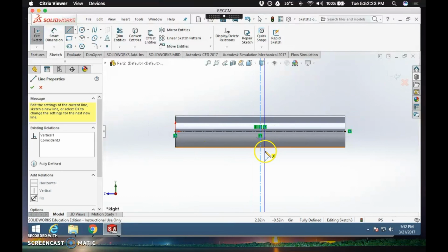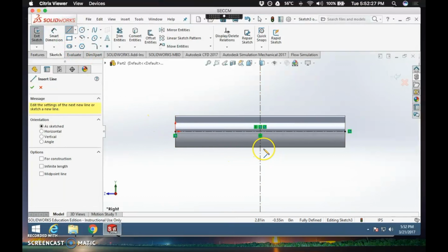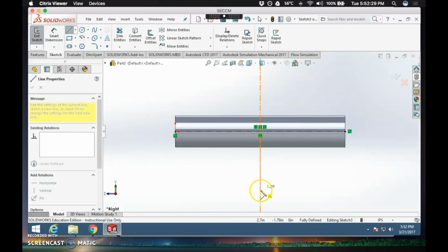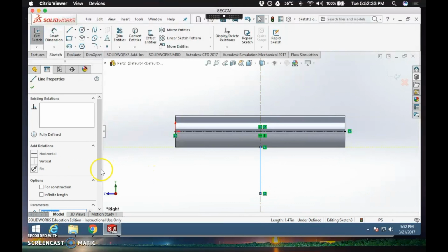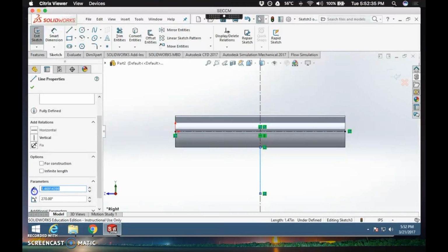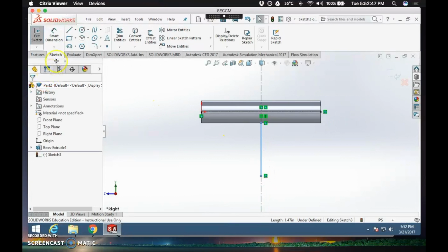And then what I'm going to do here is I'm going to create a sketch so I can find the center of it, create some center line going vertically. And what I'll do is I'm going to do 2 extrusions on this center line. That's for construction. And those will both be revolved, or have an extruded revolve around them.